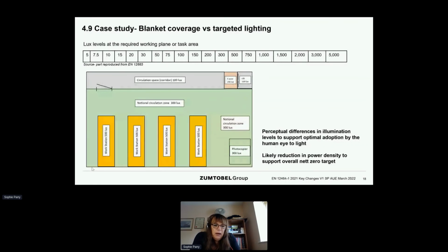So what we've got here in this green area is, well, okay, the luminaires on the ceiling, we should have a lighting control system in this day and age. What we'll do is design the whole space to 500 lux, but when we walk in a room, we create 2 lighting scenes with a lighting control system. The lights will switch on automatically, but the lights over the workstation will switch on via lighting scene 1, say, to the full design output of 500 lux. But the luminaires over the green area, where we only need 300 lux, will respond to lighting scene 2 and only operate at, say, 70% output to give us 300 lux.